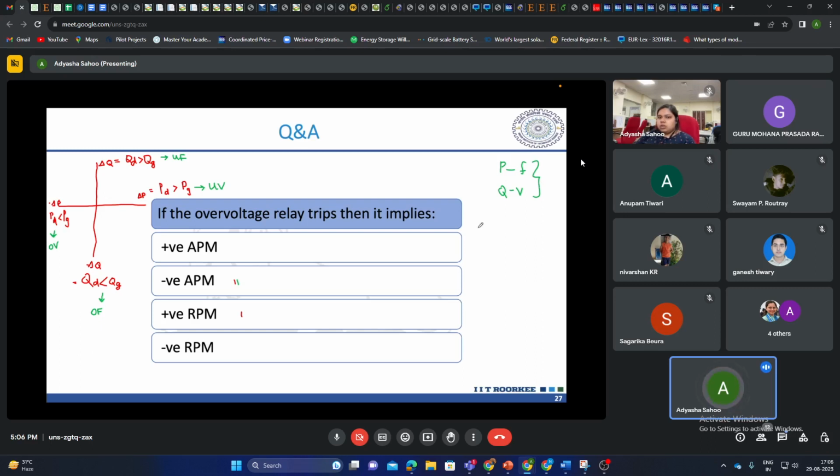Because if you remember the P and Q injection, Pi is the summation of Vi, Vk, Yik, cos of delta i minus delta k minus theta ik. Am I right?